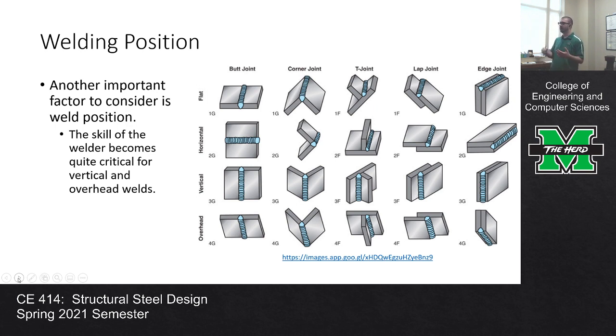If you have something that's loaded and unloaded, much like the tab of a soda can, the weld can fail by developing cracks. So that's another reason that welds can fail. Beyond that, they could just fail under load application. But we could probably be defining limit states all day for different reasons a weld fails. It also depends on the geometry and stress concentrations. We could go on from there.